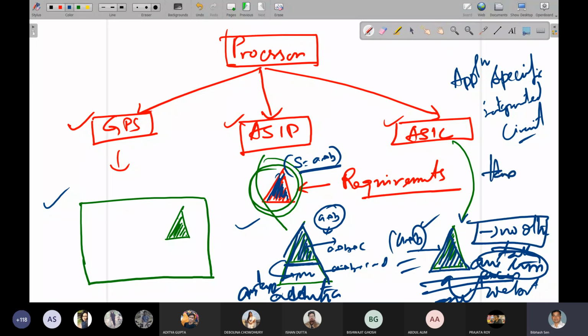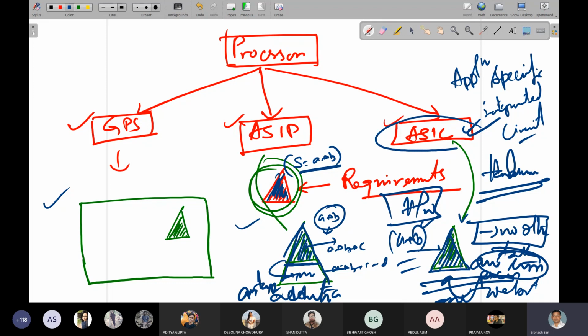So it is completely hardware. That means you can say in an application specific integrated circuit, it is very fast for only that application. No other application you can make. So that is the ASIC, and it is completely chip based. If your chip performs only JPEG coding, it can do only JPEG coding. No other coding is possible or viable using this chip. Understand this point? Clear?